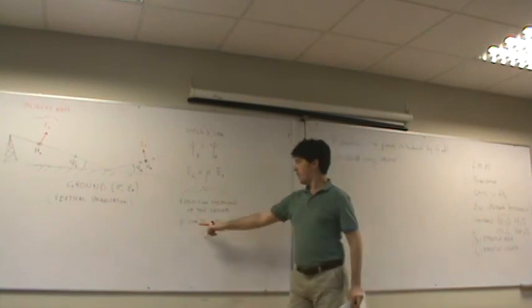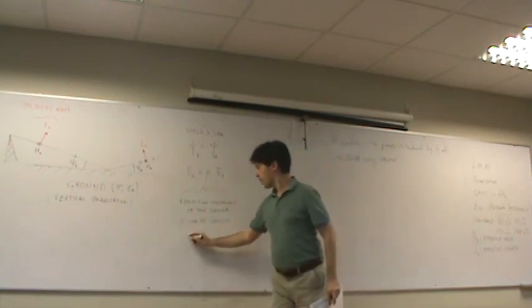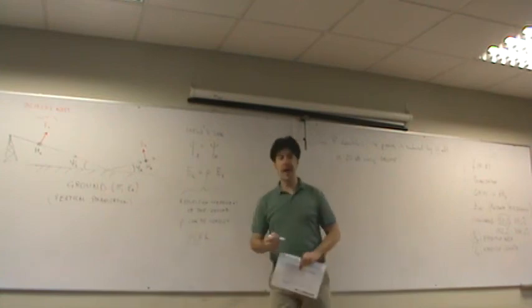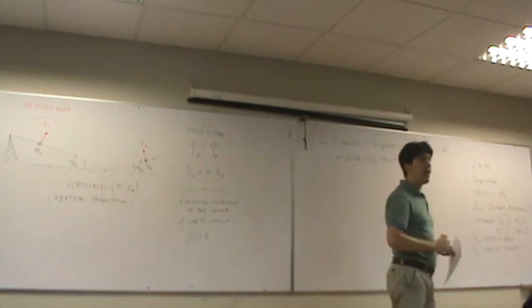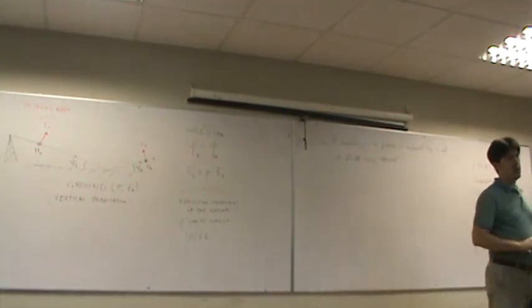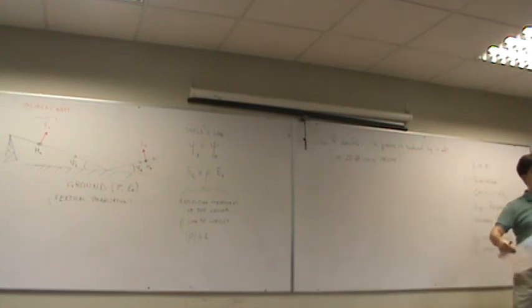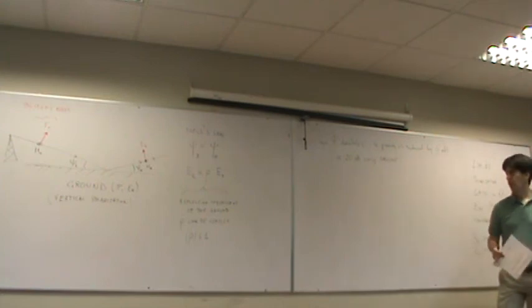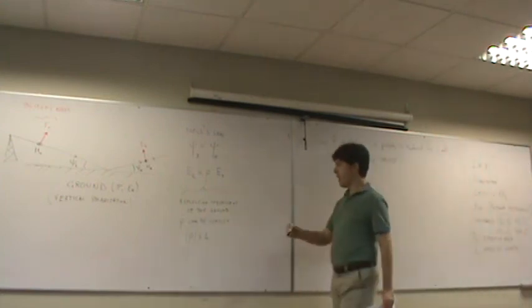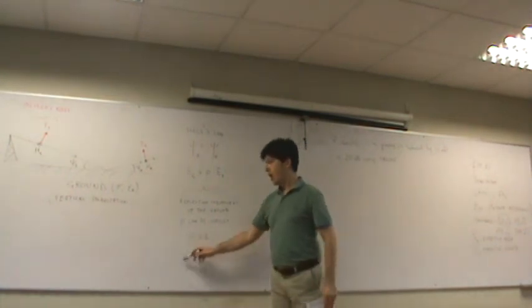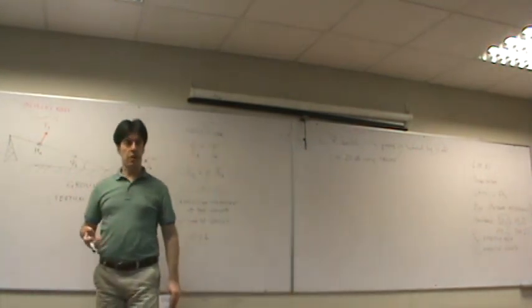Please note that the absolute value of the reflection coefficient must be less than or equal to 1. In other words, it is not possible that the reflected wave is stronger than the incident wave. Otherwise, it would be carrying more power than the incident, and this is not feasible. I tell you because maybe we have to do some calculations, and we all make mistakes in calculations.